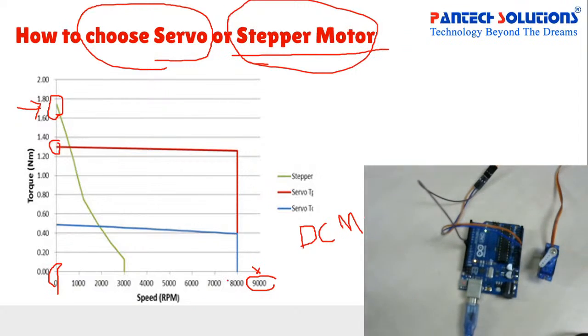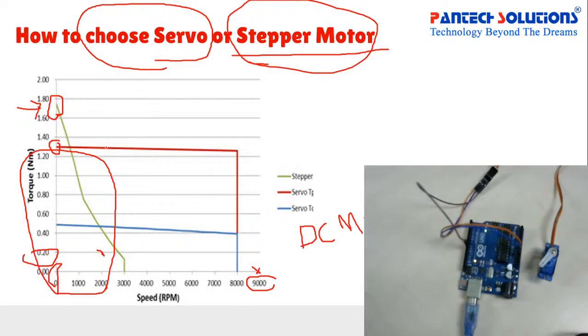Wherever you need high speed, within this range you can choose the load. For example, 2000 RPM, but the load is about 2 kilo only, 0.2 Newton meter only, then you can choose the stepper motor. In the same condition, 2000 RPM, if we have to increase the load up to 1 Newton meter, then we have to choose the servo motor.